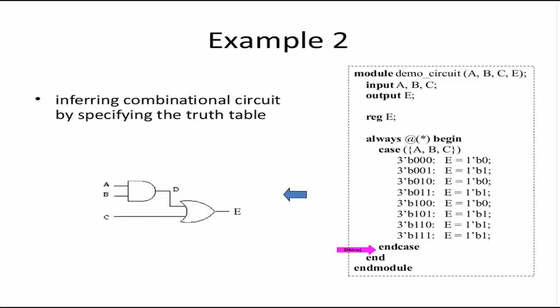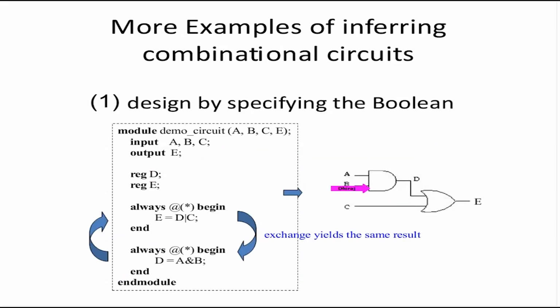So that is why you can actually do a more sophisticated RTL coding and not worry about the optimization, because the tools are very good at optimization. They will come up with a lower area circuit. Here the important thing is to make sure that you mention all the cases, and as the number of inputs increase, this is not too easy.